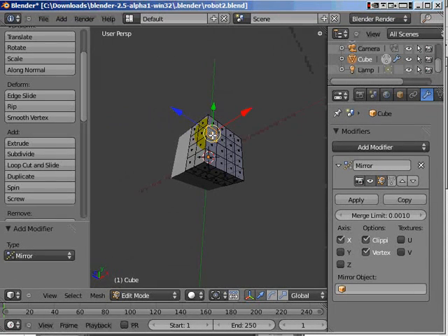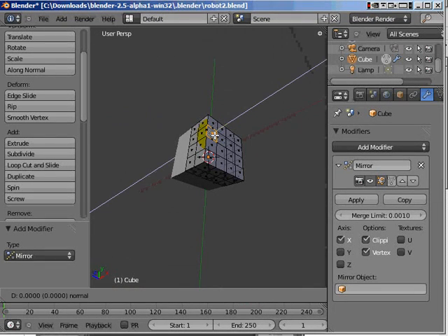We're going to be turning this into an arm, which is going to extrude out in this direction here. We know already that if we press the E key, it will extrude that square out, and that's exactly what I'm doing right now, E. Now, depending on what version of Blender you have, there may be a list that comes up. At the moment, we're selecting an individual face, and we're extruding it outwards.